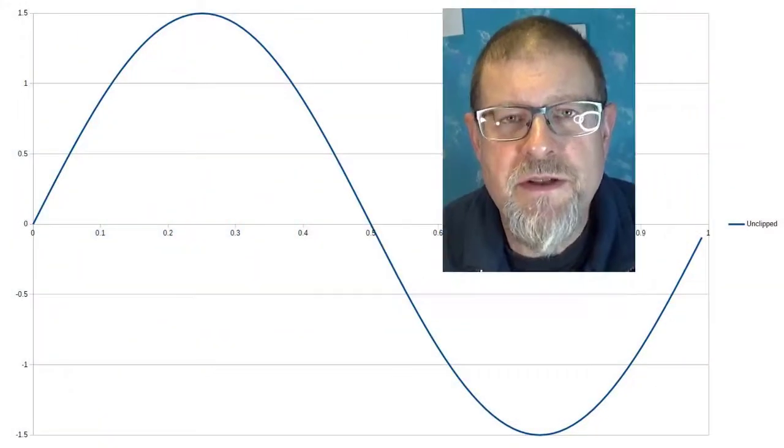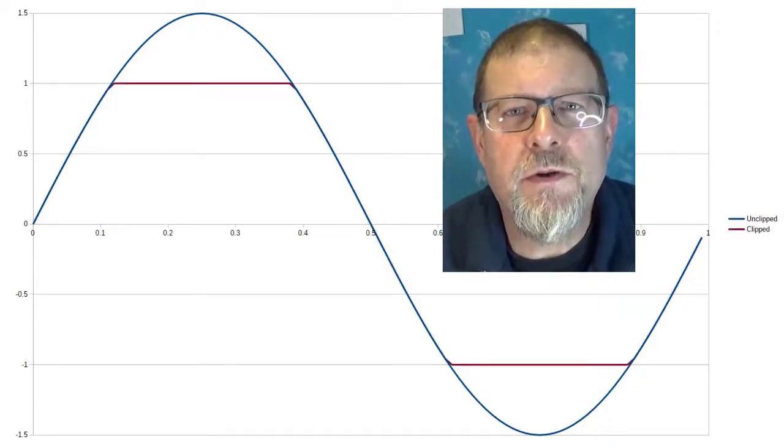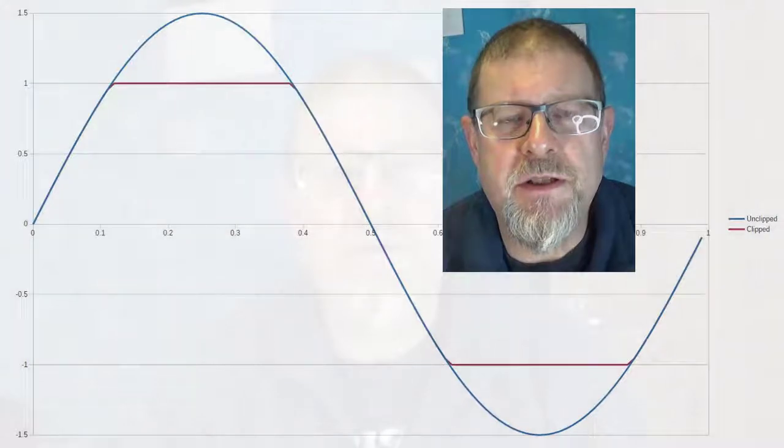Every electrical audio signal has an upper limit set by the supply voltage of the circuits that are carrying it. When the signal reaches this limit, it will clip, and this clipping will result in distortion, which will be harmonics of the signal. If we were designing an amplifier, we wouldn't want this to happen at all. However, in musical applications we can use this to good effect.